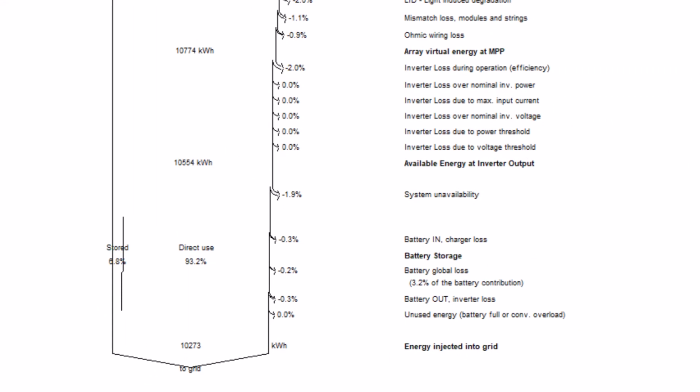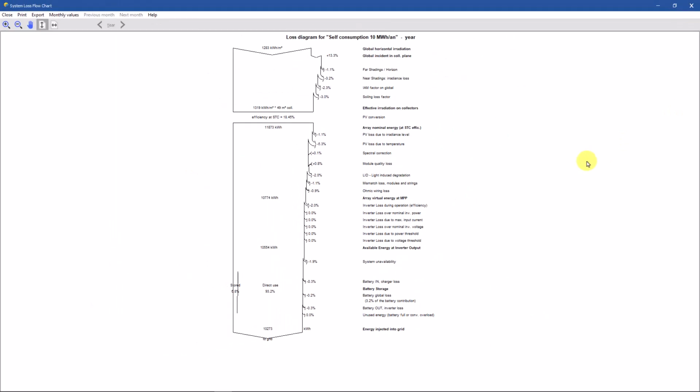You can see below the energy flux is divided by 2. There is the direct energy injected to the grid, and there is the energy stored. With this tool, you can avoid wasting energy that was produced when there was too much sunlight. To use this method, you charge up a battery as soon as the solar power hits a certain level, and then use the battery when the solar power drops below that level. The battery only gets charged by solar power, not from the regular power grid.